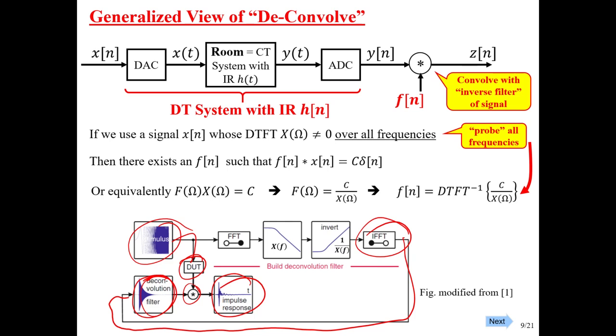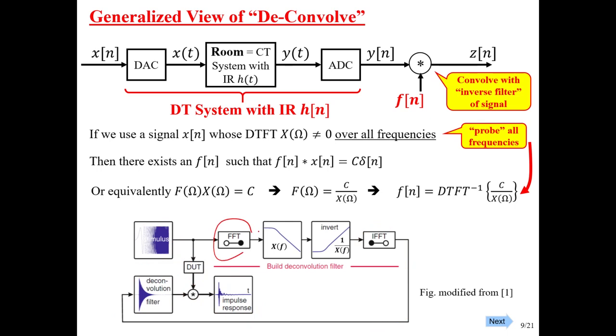Now, there are some practical issues to come up with here when using the FFT, and technically you're using the DFT. The FFT is just a fast algorithm to compute it. You're going to have to pay attention to zero padding and all sorts of other things, windows and so forth. So there are some practical gotchas there, but this is the basic idea.